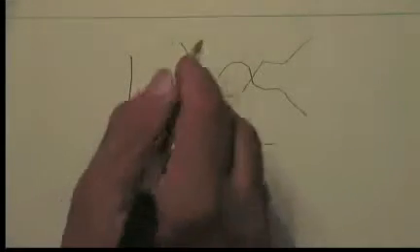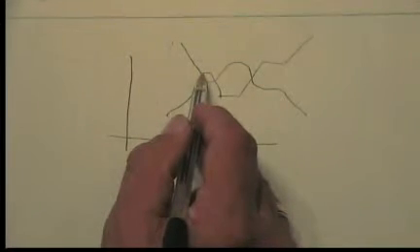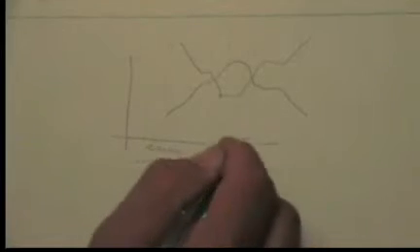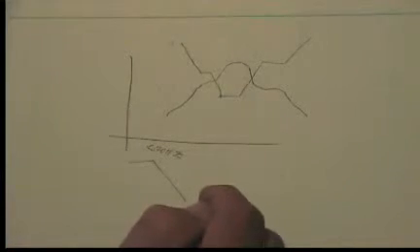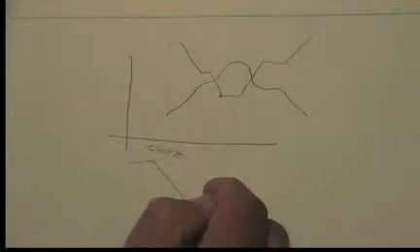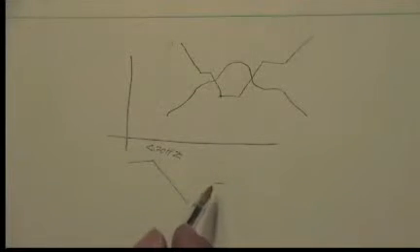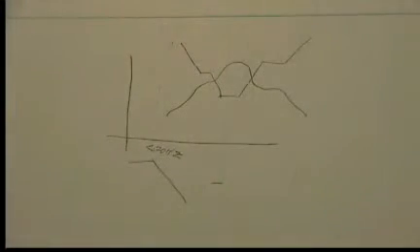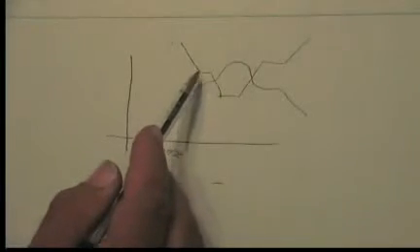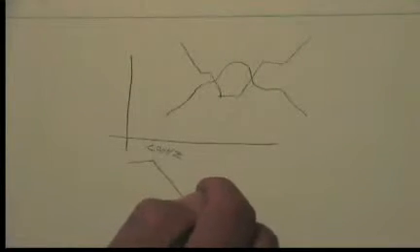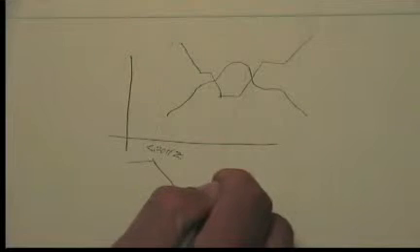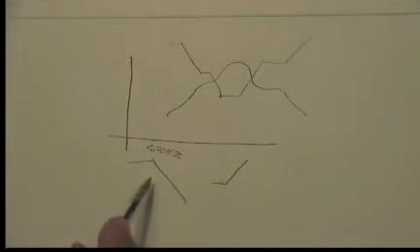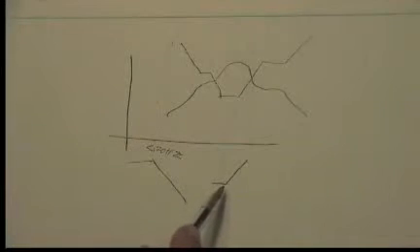I'm going to follow that by a place where it flattens out. And in order to make this flatten out, I have to cascade it with another stage, which is going to have a response that has to cancel this particular fall with a rise of its own. The rise here cancels the fall there, put them together.